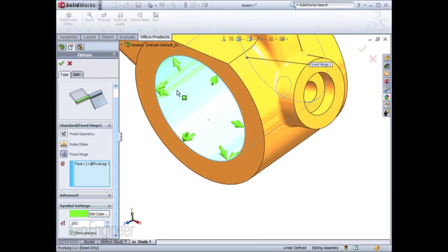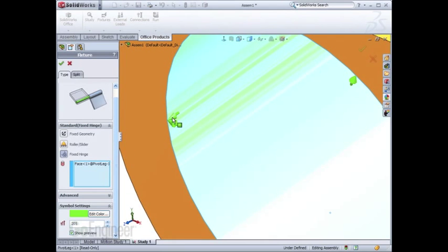You'll also notice another restraint created by the hinge restraint, and that's an axial restraint on the cylinder. So the cylindrical face will not be able to translate in its axial direction, either in the positive or in the negative direction. Again, the preview gives us a good idea of what will be allowable. So basically we only have one rotation in the Z-axis that's available around this cylinder.